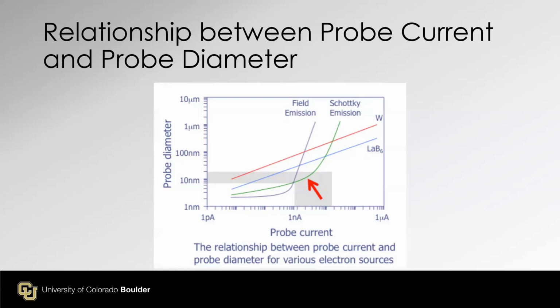Or if you need to characterize the E-beam resist pattern, I would use AFM. It's tedious. You have to find a particular area. It has its own issues, but it does not damage. It does not change while we are looking at it. So AFM was the one I used a lot to check my resist pattern. Once it's transferred, I can put it in SEM. No issue.